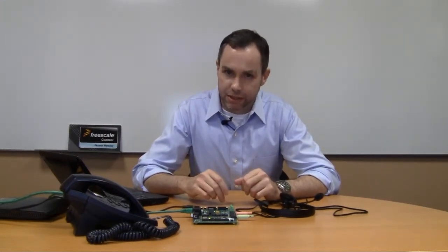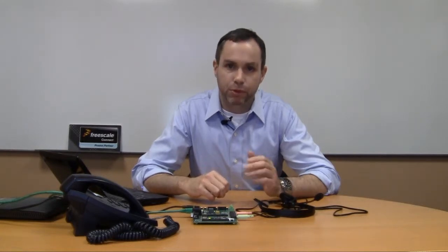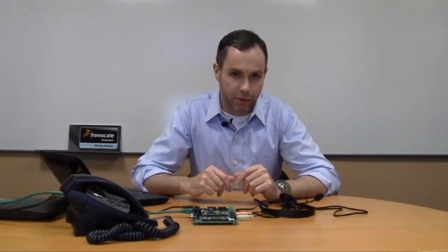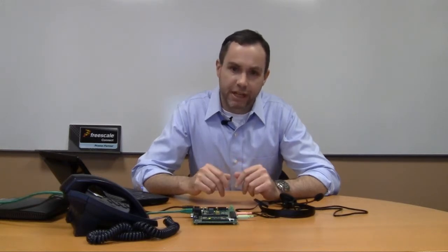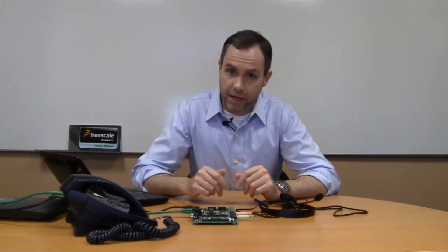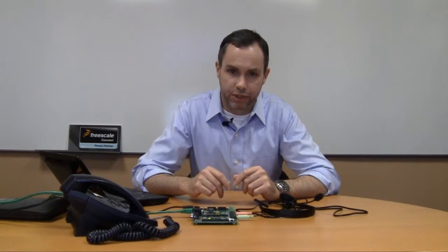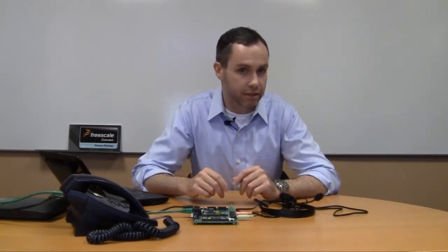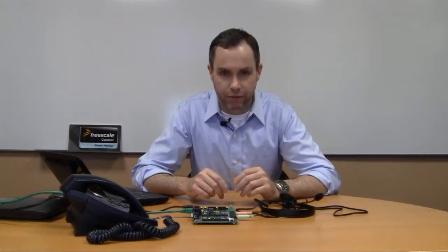The uCMK60 supports two operating modes. It supports an autonomous operating mode and a controlled operating mode. In another video, I've covered off the autonomous operating mode. Today, I'm going to talk specifically about the controlled operating mode. This mode is intended for applications that need to be supervised or controlled by a remote host. The host can be connected to the device either using a TCP/IP-based socket connection or over a serial UART.